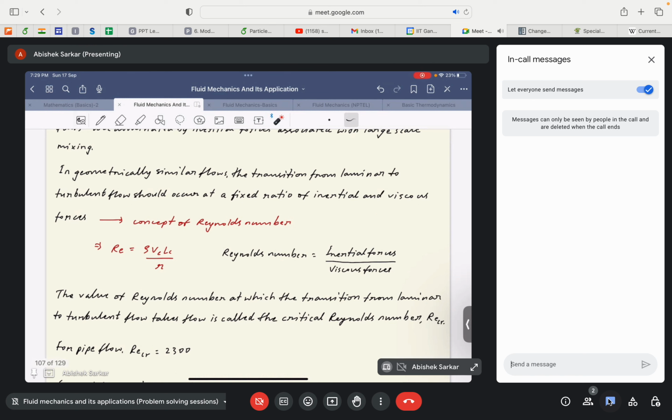Okay, so that's why these forces are viscous dominated. Since the viscous forces dominate, you can clearly say that if viscous forces are higher or almost equivalent to the inertial forces that exist in the flow field, the value of Reynolds number would actually be low, right? If the denominator is high, then you can clearly see that the Reynolds number would go down.